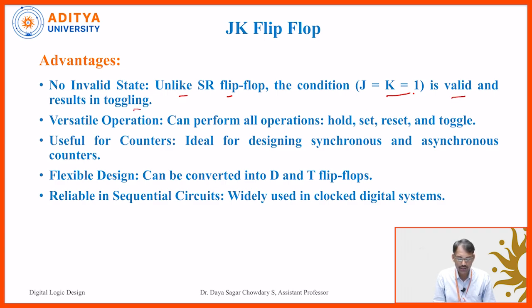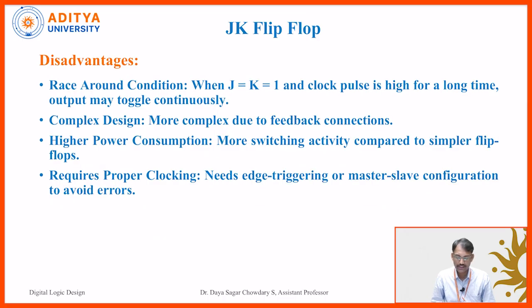Now, versatile operation: it can perform all operations like hold, set, reset, and finally the toggle condition. And useful for counters, so most of the counter circuits use JK flip-flops, ideal for designing synchronous and asynchronous counters. And flexible design: this can be converted into D and T flip-flops also. And reliable in sequential circuits, widely used in clocked digital systems. So these are the advantages.